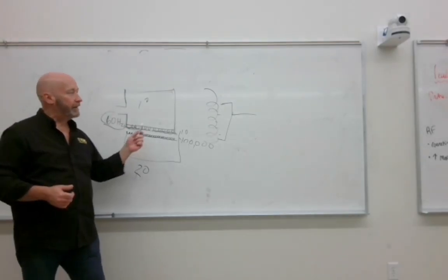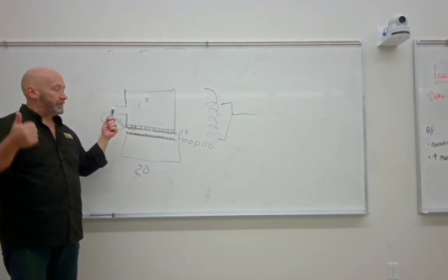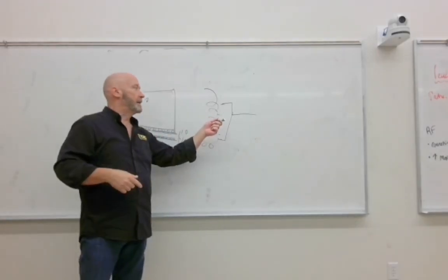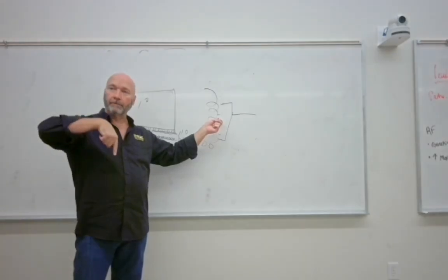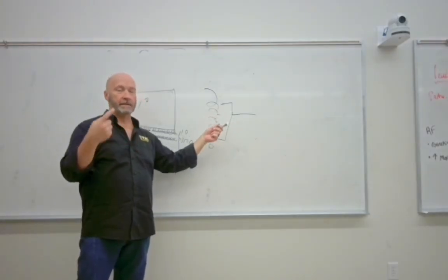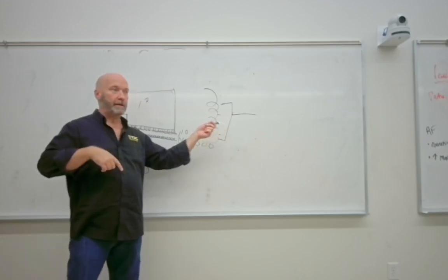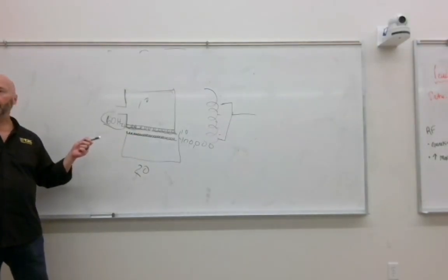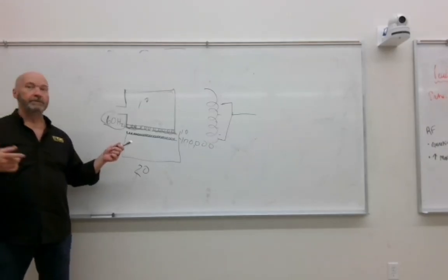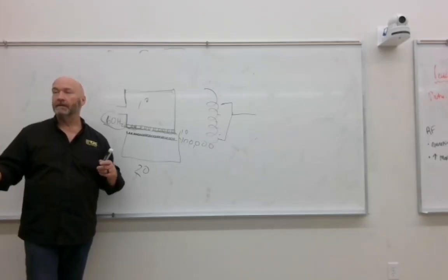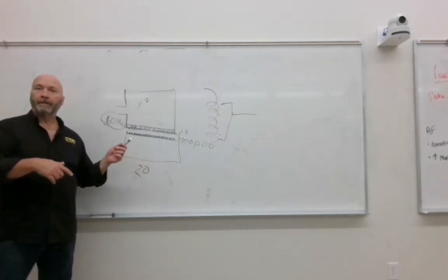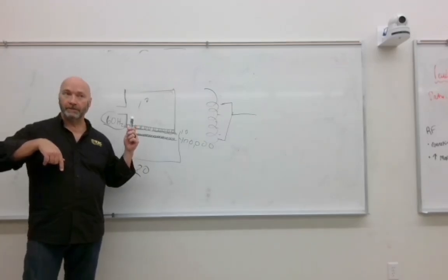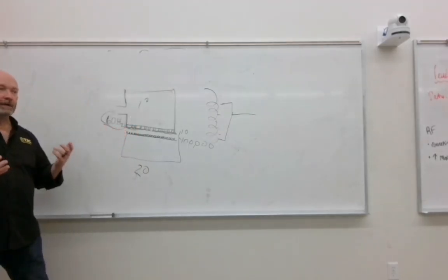So we have the auto transformer as one. We have the step up transformer as one. Okay, let's back up to this. Auto transformer steps up or down voltage, depending on where we put the contacts on the secondary side. So it can go up or go down. Step up transformer only goes in one direction. That is increase in voltage. We're going to increase voltage on a magnitude of thousands. Step down transformer has a turns ratio where the primary side is greater than the secondary side, so voltage goes down, right?